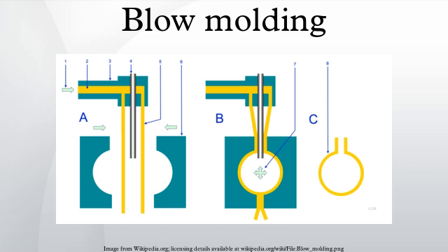Injection stretch blow molding process. This has 2 main different methods, namely single-stage and 2-stage process. Single-stage process is again broken down into 3-station and 4-station machines. In the 2-stage injection stretch blow molding process, the plastic is first molded into a preform using the injection molding process. These preforms are produced with the necks of the bottles, including threads on one end. These preforms are packaged, and fed later into a reheat stretch blow molding machine.